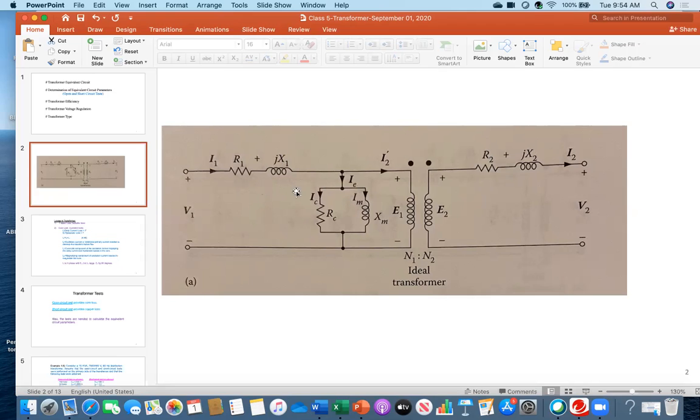So you see what is happening. You are applying voltage, this means current I is flowing, that is fine. And then I2 prime, that current is going actually to the coil. But this portion is representing that magnetic core material. You see, I have given the name I subscript phi, and it has two components.